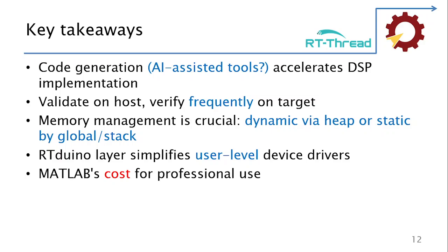So the key takeaway here is that we can use code generation from MATLAB, and this will assist us in working on the DSP part. Yes, we need to validate first on the host that everything looks good, and MATLAB helps us with this because it comes with a lot of functions that allow you to validate your algorithm. And then don't forget that we have to work on the target as well, and the key point is the memory.